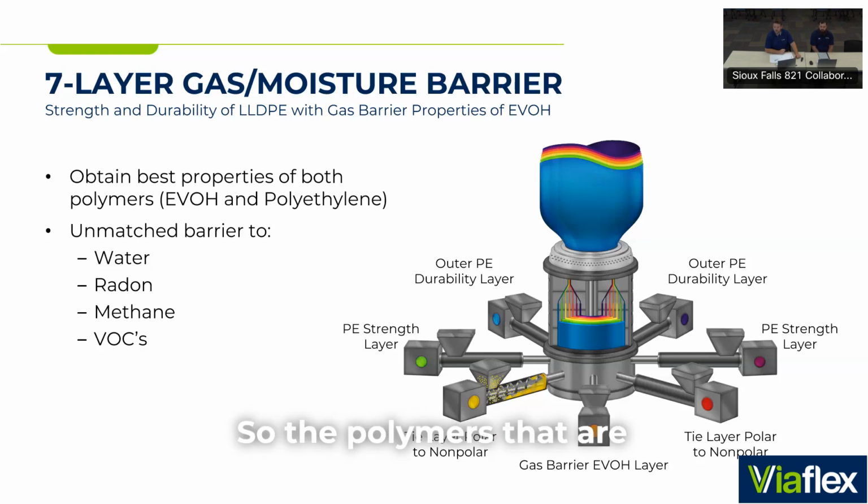I can, yeah. So the polymers that are used in designing the 20 mil film provide for all specifications for ASTM E1745, which is your underslab vapor barrier standard, to be met and exceeded without having to go to a 60 mil product. The 60 mil HDPE does meet all those also.